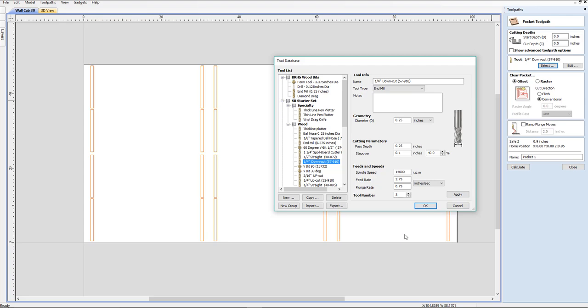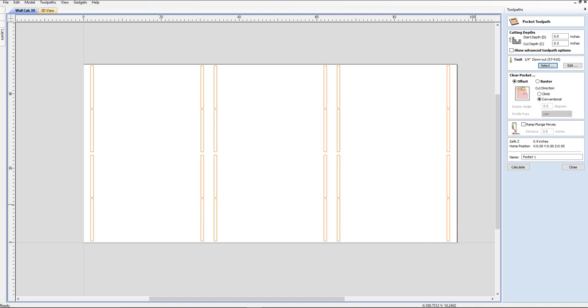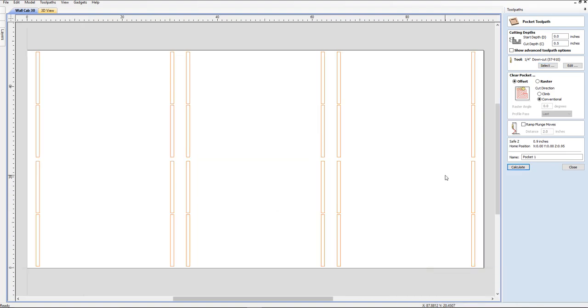Now, if you are manually adjusting your spindle, like for example in a desktop Max, or if you had a Porter cable router, you'll be setting that speed up manually. But your PRS alphas with speed control will automatically adjust the RPM to whatever you have here. So we want to find out what's going to be the best. So what we're going to be doing here, I'm just going to cancel this for just a second. Once we hit cancel, we're back in our pocket toolpath tab.